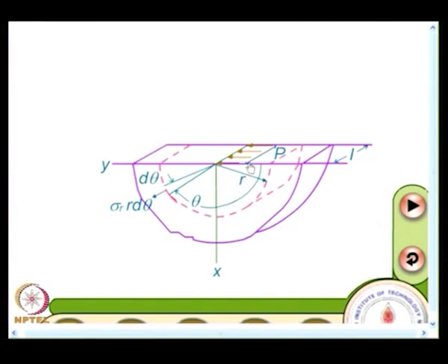Theta is defined from the reference point as the loading. Loading is horizontal, you measure theta from this, loading is vertical, measure theta from this, loading is inclined, measure theta from the axis. So, if you recognize this, you get a family of solutions for important problems just by redefining how you measure theta. For all these cases you get solution.